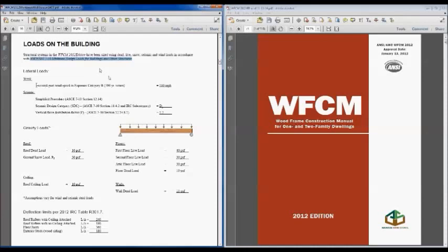And for this example, we've got a pretty high wind speed, 160 mile per hour exposure B. And in retrospect, I wish we had chosen 150 exposure B, but I think I mentioned earlier there's at least one place up in the Aleutians in Alaska that has a couple of these load combinations. I think down in Charleston, South Carolina, they've actually gone with 150 mile per hour exposure B. So I guess the bottom line is if we can make it work for 160, we know it's going to work for other wind loads around the country.